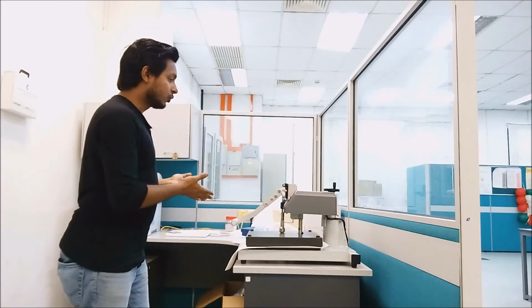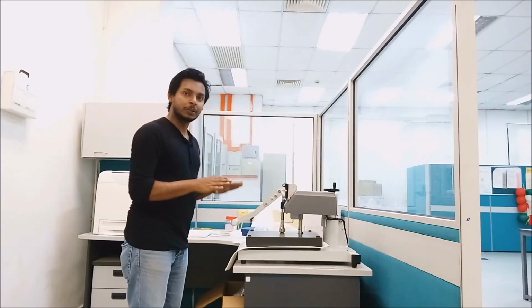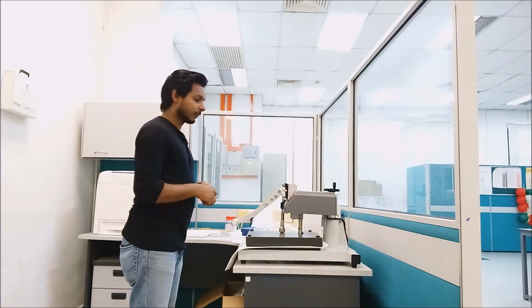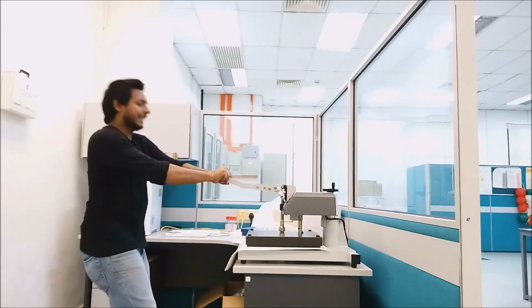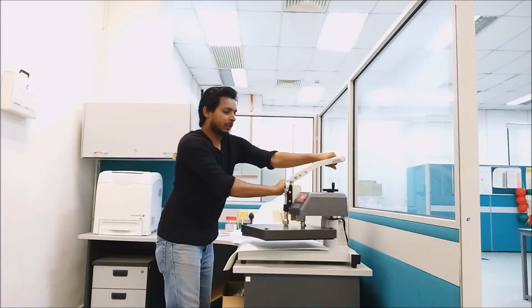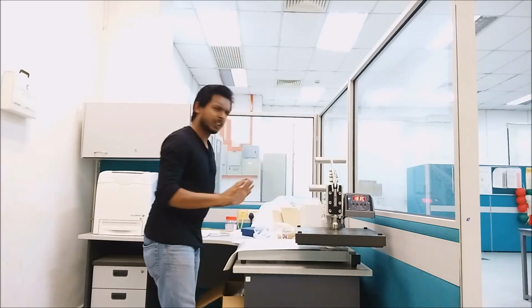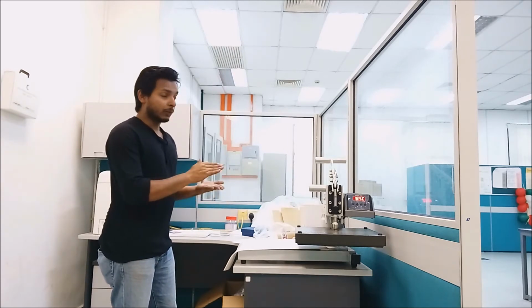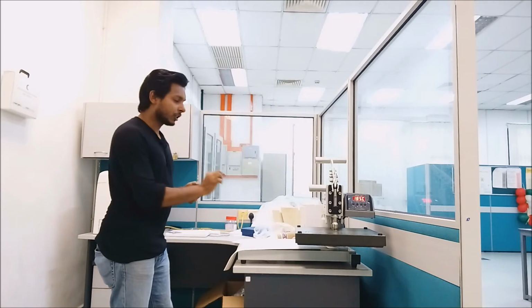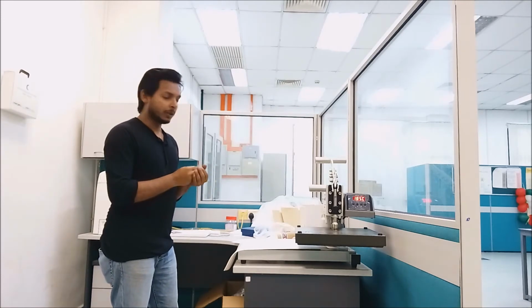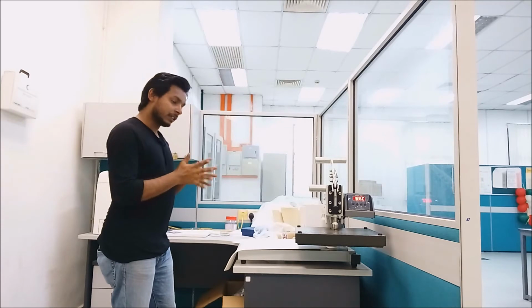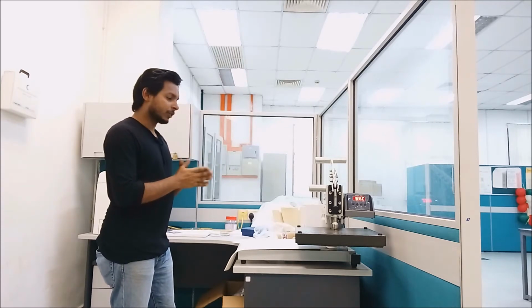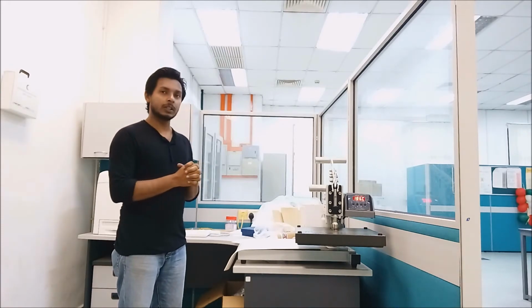So now we are very close to finishing our heat pressing. Now it will give an alarm. Yes. So we will release this handle and release this plate. Now we have to wait for a while because it's very hot, and the substrate along with the copper layers are very hot. You cannot touch them with your bare hand, that will burn your fingers. So let's wait for a while, and after this thing cools, we will move to the next step. That is very important, the etching process, a chemical reaction.